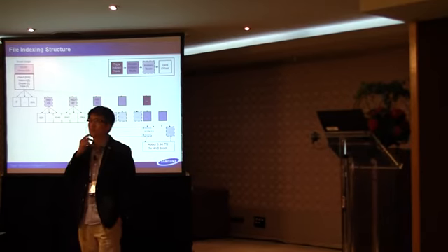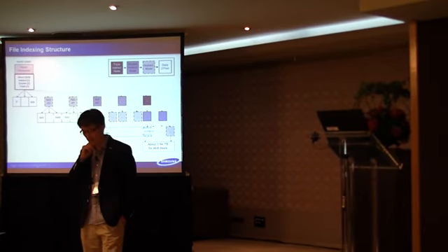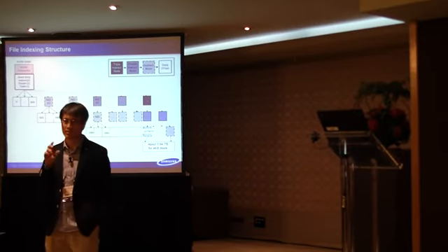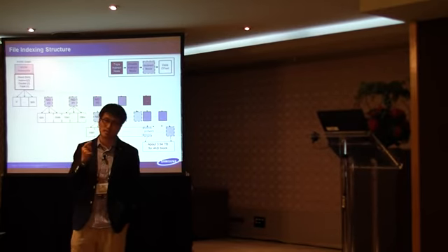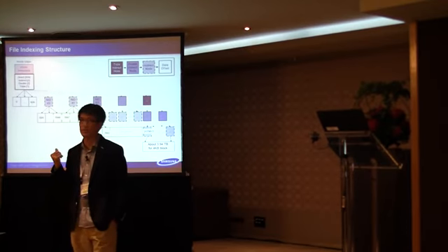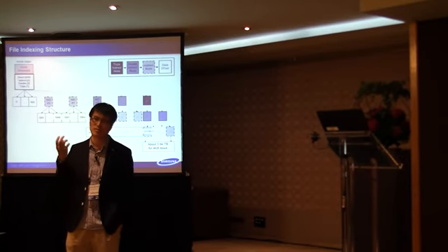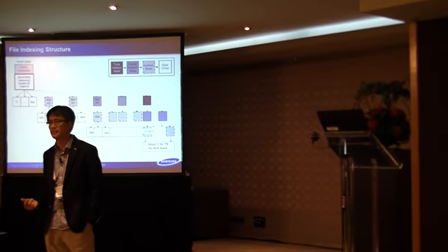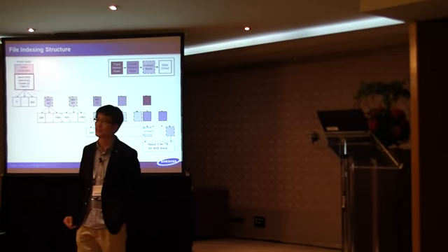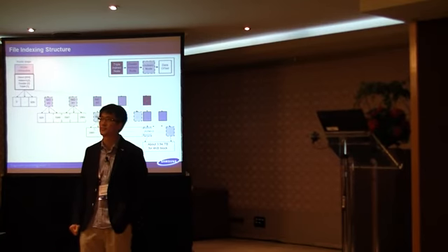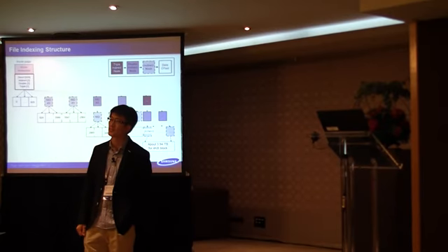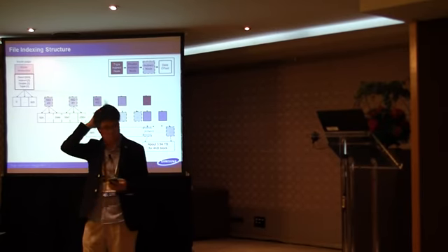By longevity, do you mean the lifetime of that? Yeah, sequential write is also good for longevity. So I think this kind of log-structured design for the FTL is good for performance and also lifetime, in both aspects. Even higher performing writes, yeah, because it should decrease the number of erases. So the same thing they're doing to increase write performance is going to decrease the number of erases, which should improve longevity.